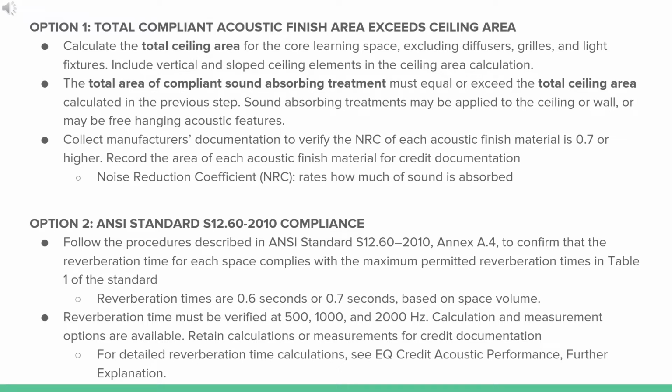Option 2, ANSI Standard S12.60-2010 compliance. Follow the procedures described in Annex D.4 to confirm the reverberation times for each space comply with the maximum permitted reverberation times in Table 1 of the standard. Reverberation time must be verified at 500, 1000, and 2000 Hz.